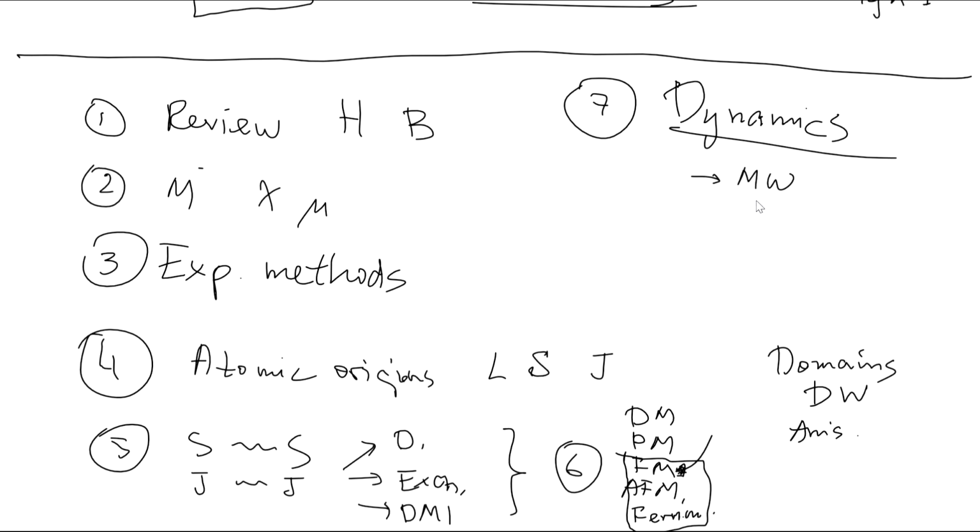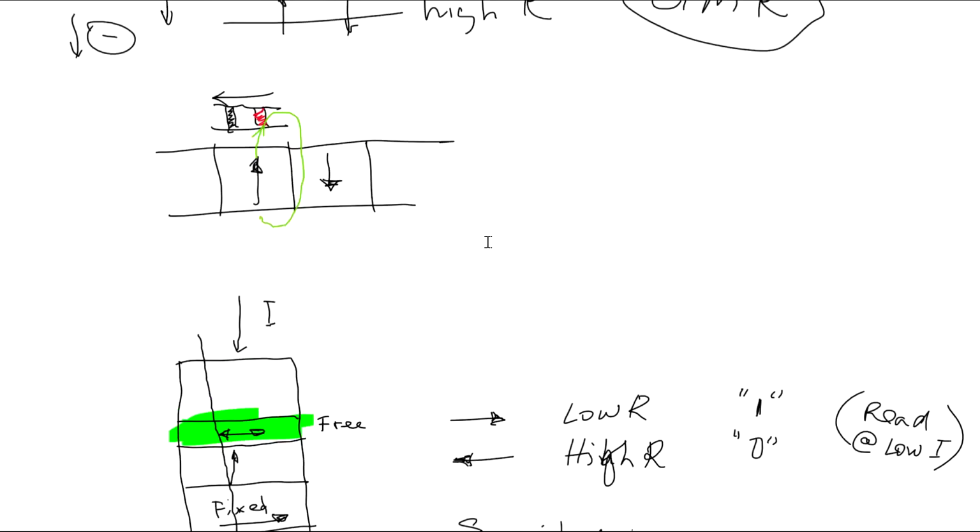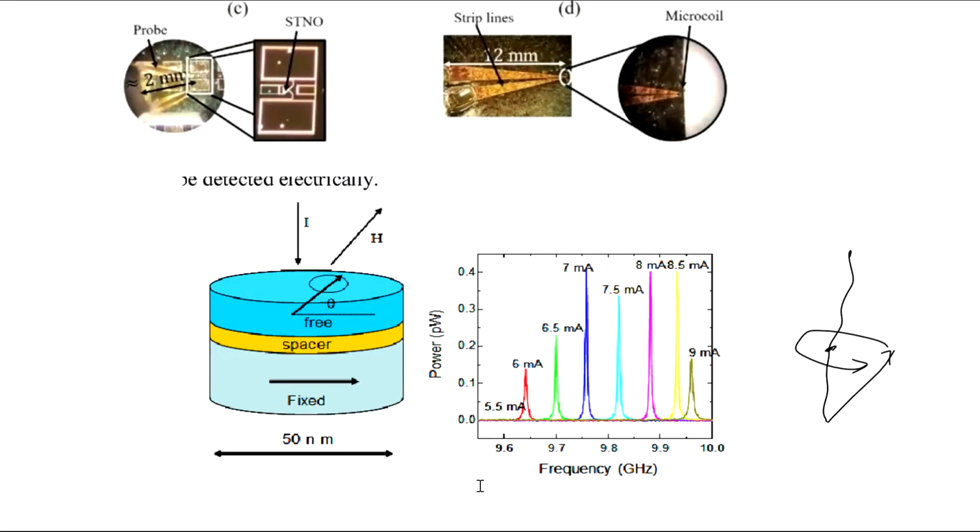Microwave applications are essential, and magnetic materials are essential because if you look at these spin torque oscillators, look at frequencies, they're all in the gigahertz range. So these are microwaves. And what it means is that this device can be used to generate microwave signals. And it can be tuned because you drive different current through the spin torque, you change the oscillation frequency. And it can be engineered to oscillate at different frequencies.